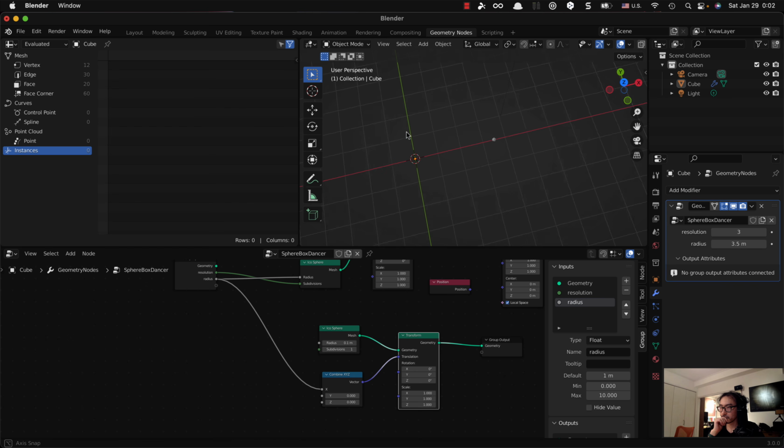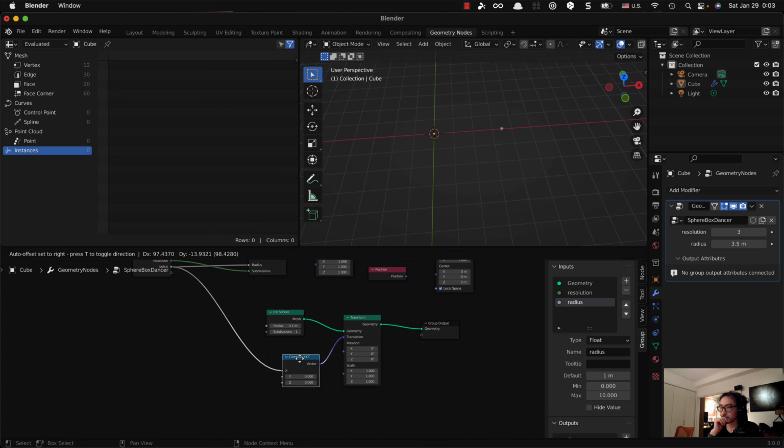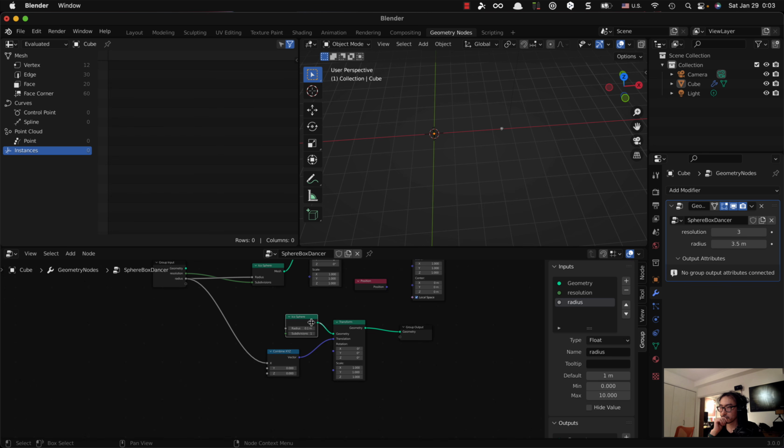Now that's good. The next thing you want to do is rotate this point clockwise or counterclockwise using the z-axis. To do that, you could use the same Transform if you're dealing with geometry, but in this case you don't really want to rotate the geometry itself, but the vector value, which doesn't have any geometry information.